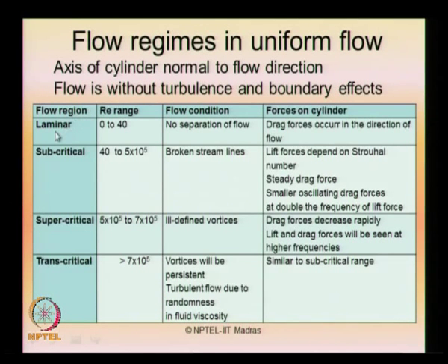If you look at the laminar region, the drag forces are seen to occur in the direction of flow itself, whereas in the subcritical region lift forces depend on the Strouhal number. You can clearly see there is a steady drag force with a very small oscillating component.